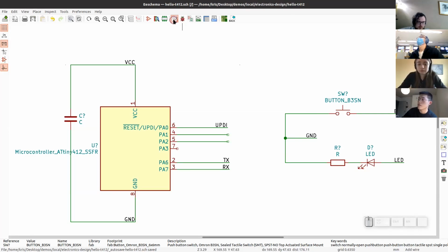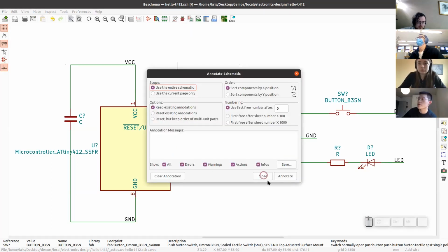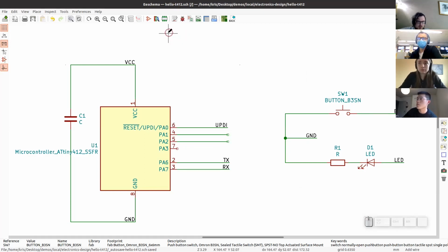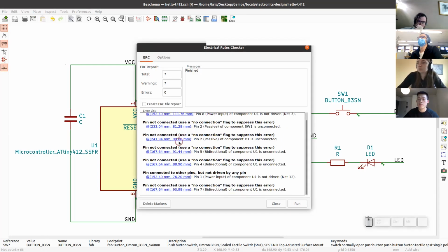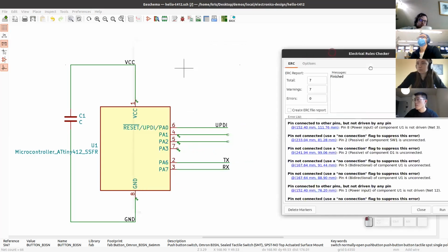If I did something wrong, for example, at the end of the wires there's a little block, I guess, which means it doesn't connect to the label. Yeah, could be. When you run this, it's going to show you what is not connected. So there are a lot of not connected pins yet, so we need to connect some.